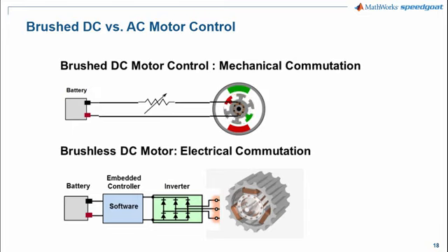The common DC or brushed motor has commutation done internally via mechanical contacts or brushes. The brushes are the parts that are sliding right here, shown in the top. As the motor turns, the brushes supply different windings to continue the motor rotation. It is a simple design to control. Apply a voltage and the motor spins. There are two simple equations that relate current, voltage, speed, and torque.